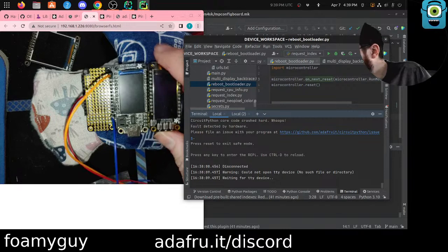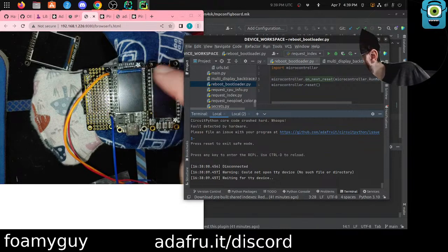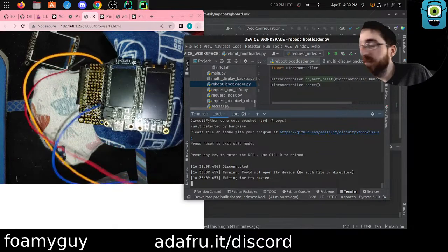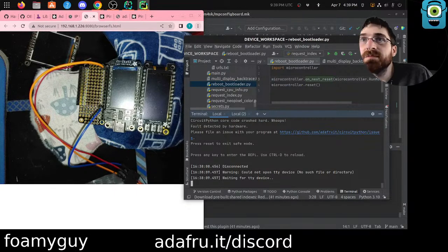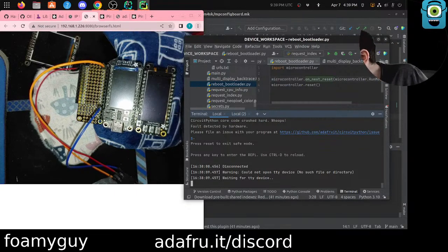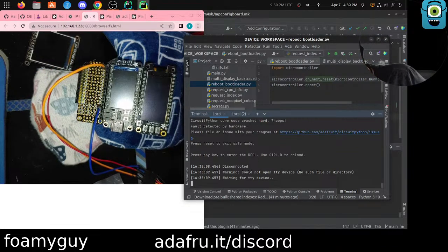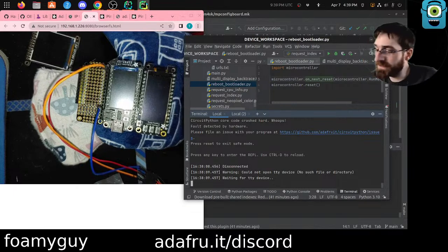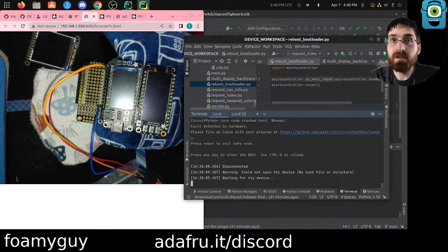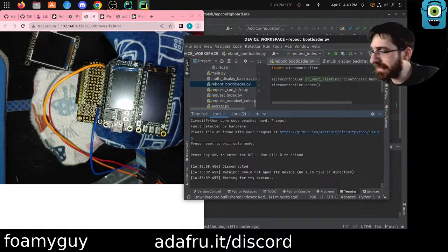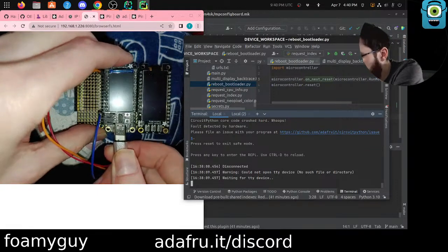If we can get the same thing to fail on this device, we can read it through the debug pin, which is like the top right pin up here. I have it connected up with these wires. There's not much to see, but they're connected with this thing, which is an FTDI cable. We can basically see more information. In particular, it spits out a hex representation of a stack trace that you can then turn into an actual stack trace using some helper script inside the core repo. So if we can get the same crash on this device, we should be able to get the stack trace for it.